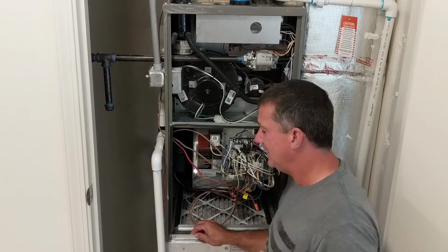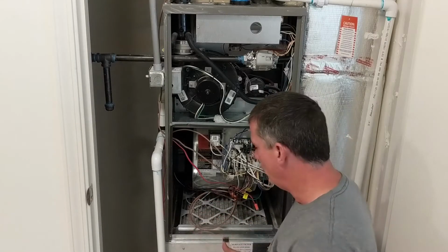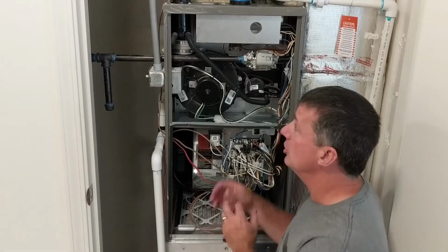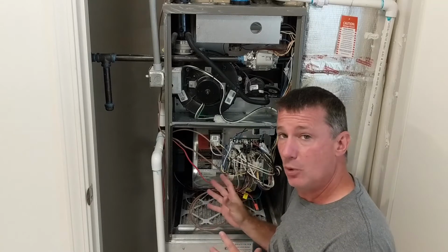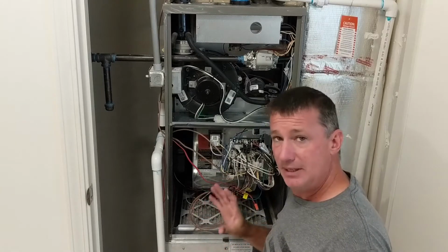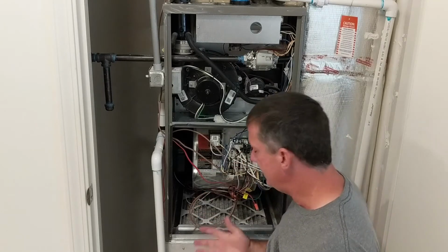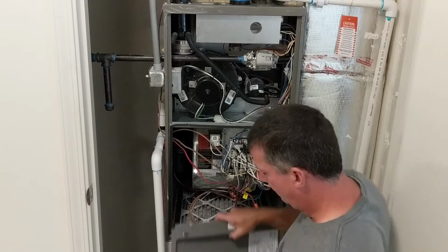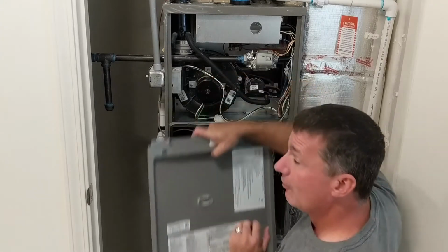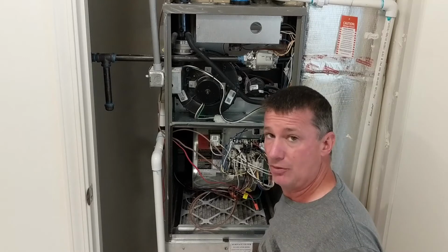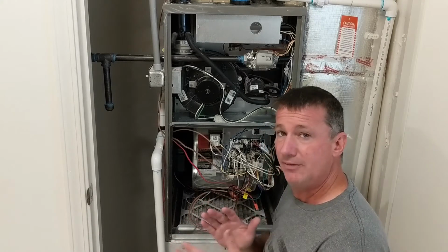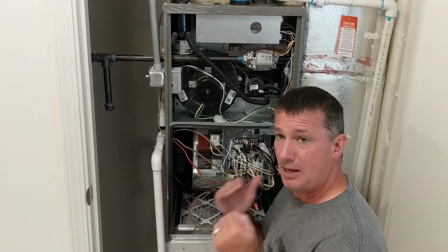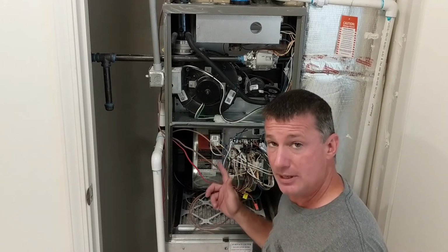Temperature rise is the change in temperature in heating mode from the return air temperature to the supply temperature, and it is specific for your piece of equipment. It's typically around a 50-degree center point, but the furnace will tell you, for instance, that this particular one has a 40 to 70 degree temperature rise, and the manufacturers will tell you that somewhere in the middle of that, around 50 to 55, is the optimum performance for that furnace.